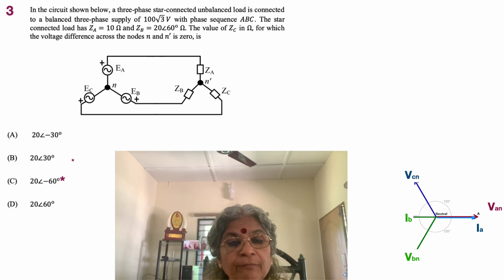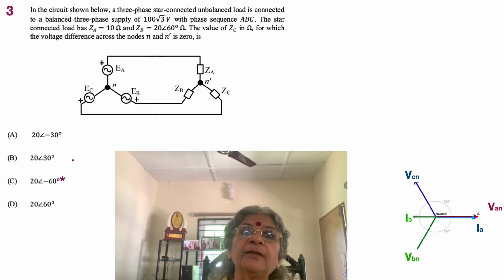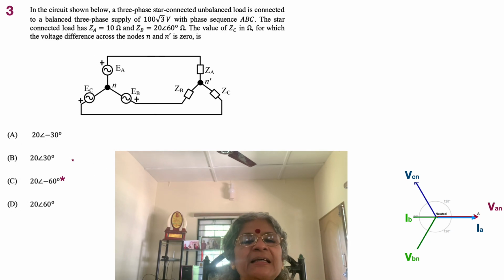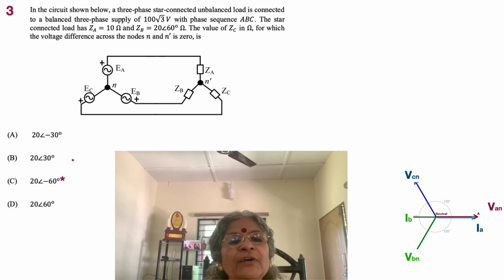So when they act together, it is clear that the vertical or imaginary components cancel off, and the horizontal component of the 10 ohms creating a current of 10 amps is now cancelled off as a result of the two 20 ohms working together, one at an angle plus 60 degrees, the other at an angle minus 60 degrees, just as we saw earlier, as also reflected in the phasor diagram shown alongside.